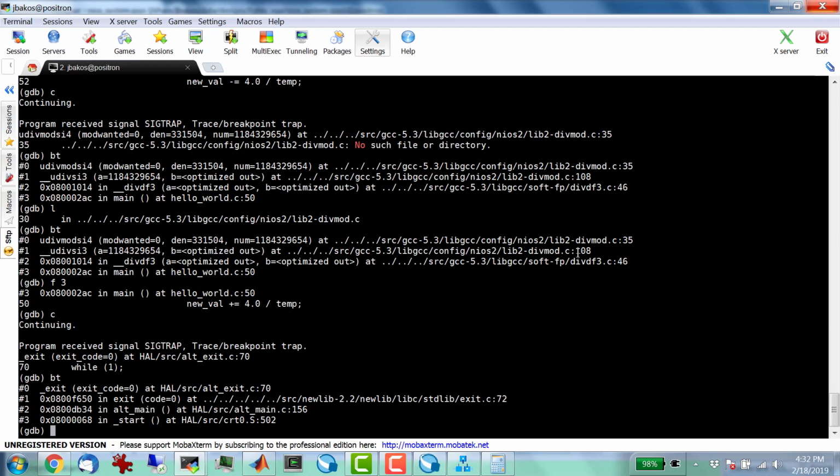If you return from your main function, there's nowhere for it to go because I don't have an operating system that could find some other use of the CPU after main exits. So instead, it goes all the way back to AltMain, which is a wrapper around the main function. It calls main, and then when you return from main, it goes back to AltMain.